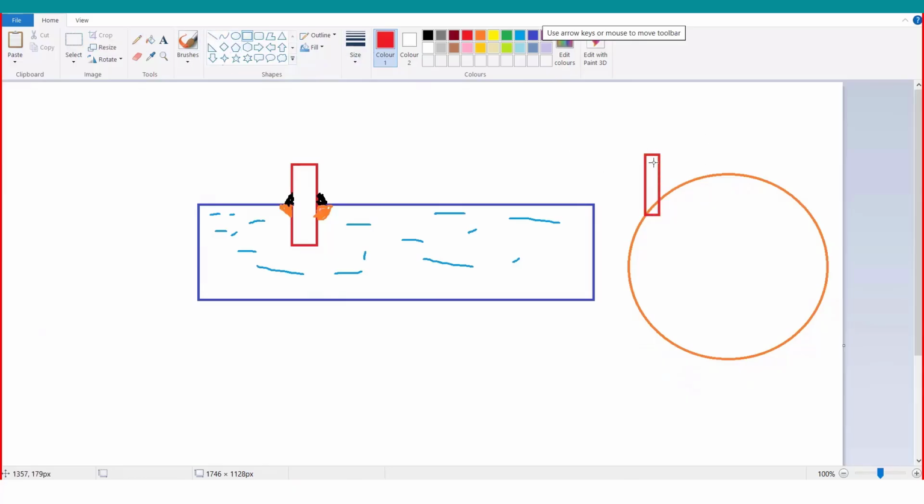If I extend the center line of this nozzle, does it pass through the center of the equipment? No. So this is called an offset nozzle. This is called a hillside nozzle, also known as an offside nozzle. If I have a nozzle like this and I extend its center line, it will pass through the center, right? So this is called a radial nozzle. And here both the center lines are parallel to one another. This is called a hillside nozzle.